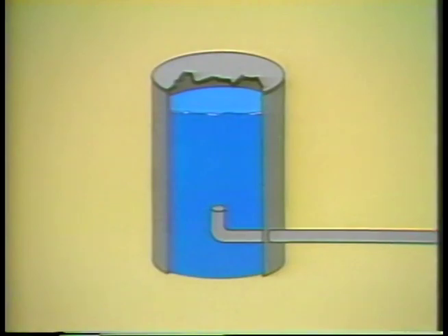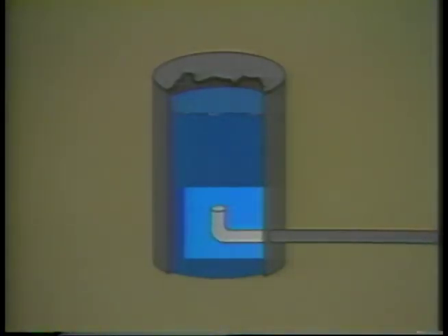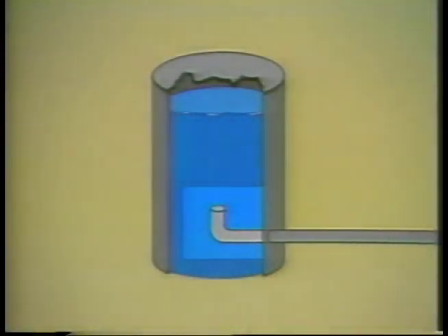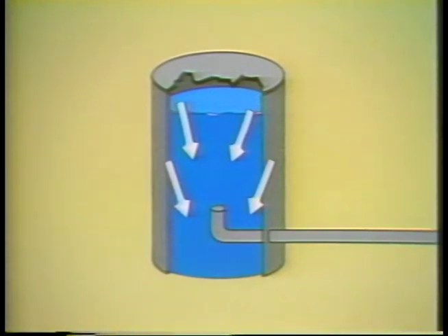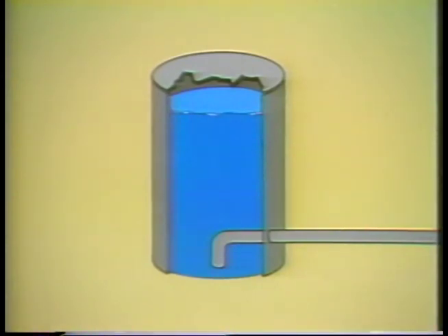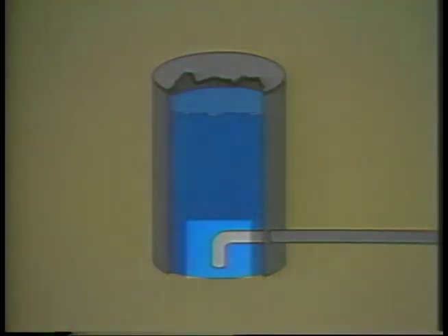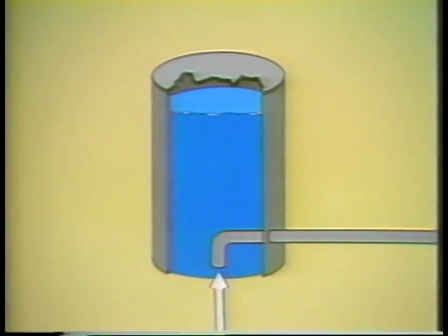Now, one thing is always true of the pressure in a tank. It's exerted in all directions. We can see this if we consider the placement of a suction pipe in a tank. The most common notion would be that the inlet to the suction would have to be placed upward in order to allow pressure to be exerted fully on the suction. But in reality, most suctions are pointed downward. And this is possible because the pressure at the point where the suction is taken is exerted equally in all directions. Therefore, the pressure upward at that same point is the same as the pressure downward, and to all sides. The direction the suction inlet faces has no effect on the pressure at the suction.